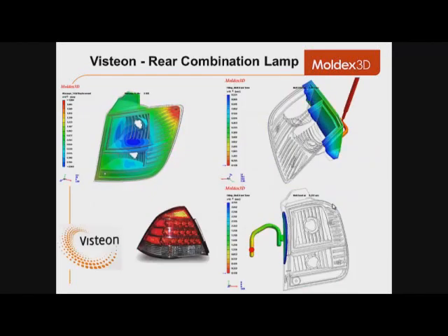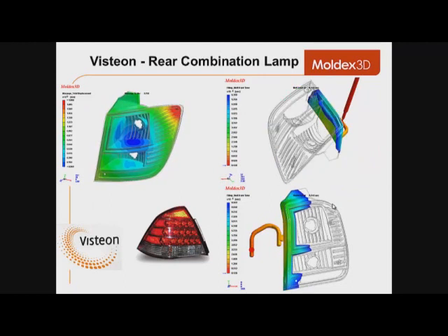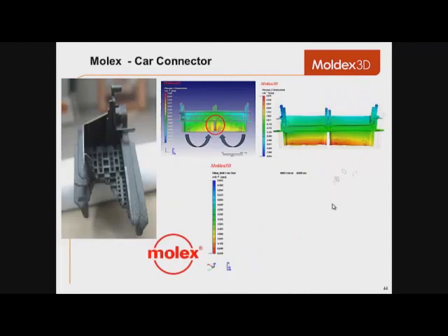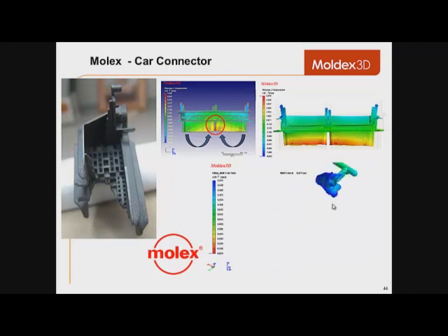Over here, this is a result from a simulation we did on a headlight. With this Molex car connector, the temperature difference between the top and bottom part was causing a warpage issue, which in turn caused this model to bend in.